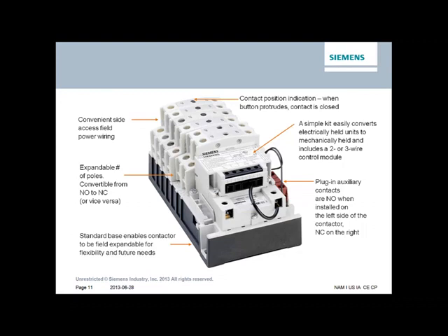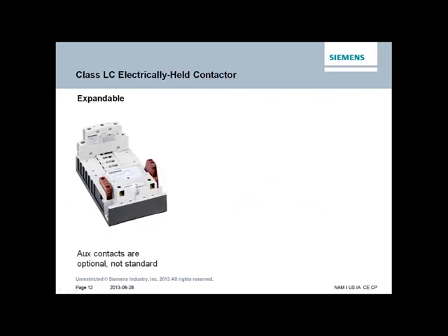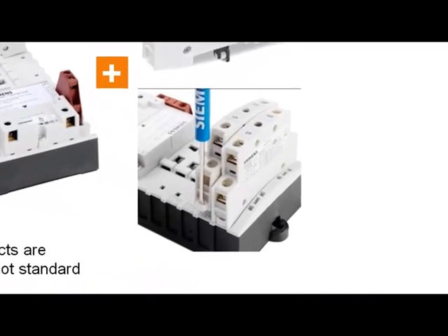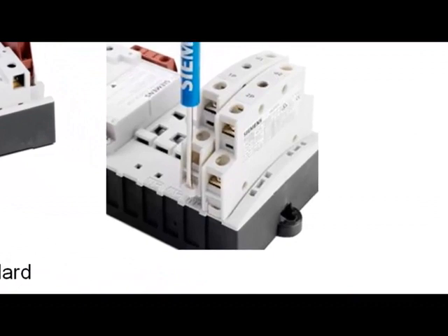Now we will demonstrate the expandability of the LC contactor. Let's start with a 2-pole LC contactor and, with the use of a simple screwdriver, you snap on the additional power poles, and within a few seconds you've added additional power poles up to 12 power poles.